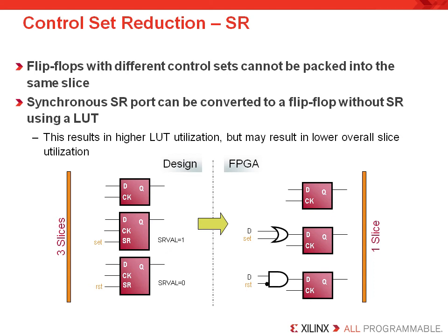So what we're getting at here is, again, we have a much better chance of being able to group this component, if it's a low fan-out control signal, with other flip-flops or other logic of different functions into the same slice or CLB, simply because the set or reset and the clock enable are synchronous. So again, it's just a very good practice. It gives the tools a lot more flexibility, better device utilization, better chance of meeting your timing. Lots of good reasons to do this.